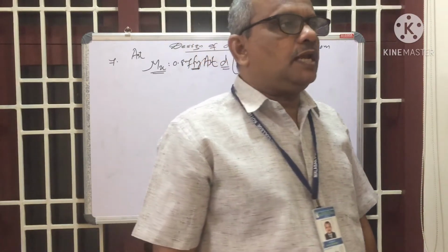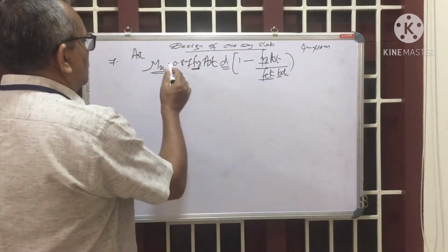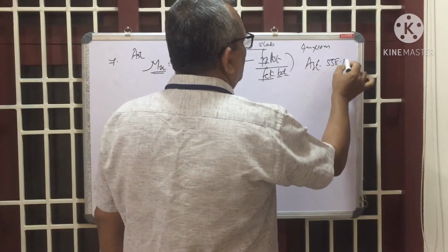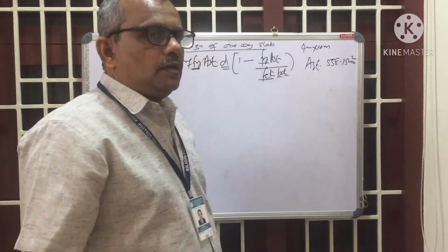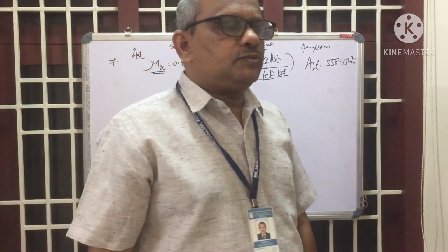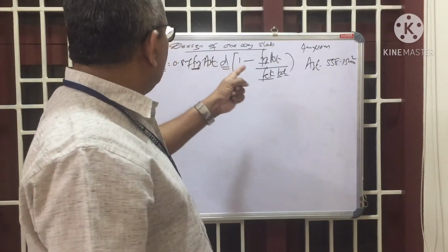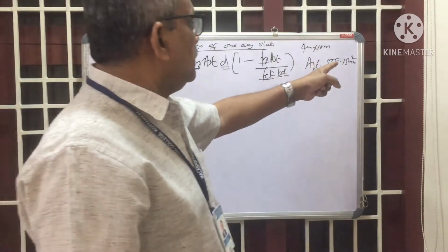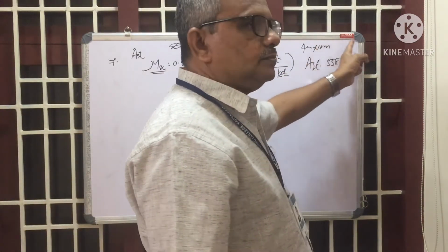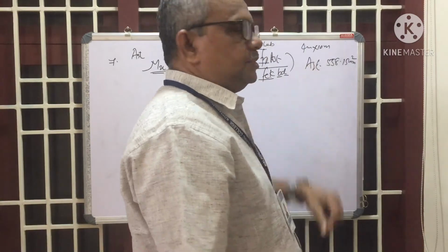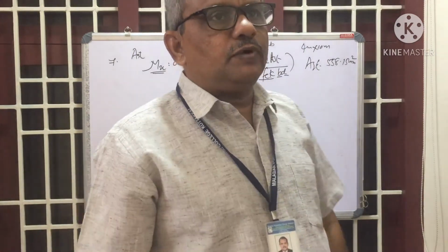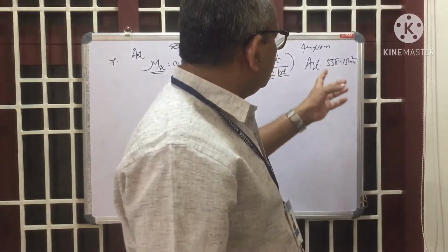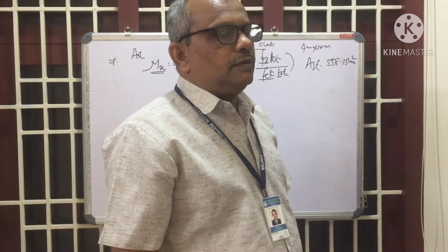Area of tension steel required. When you substitute, you will get AST equal to 558.15 mm square. You will get a quadratic equation, and by solving it you will get 2 answers. Out of the 2 values, the admissible value you can take as 558.15 mm square.